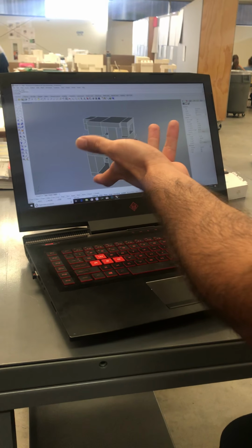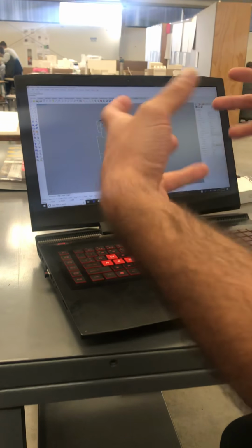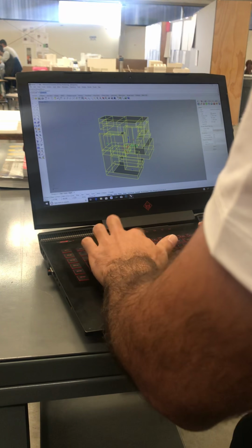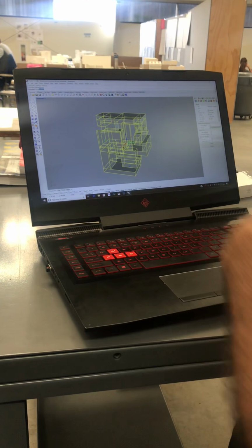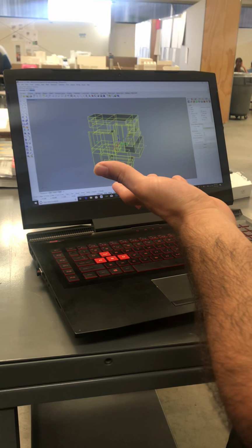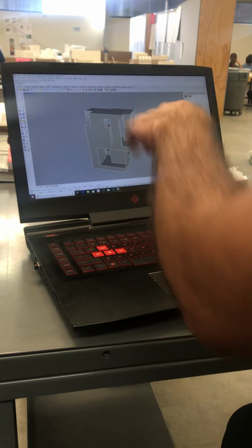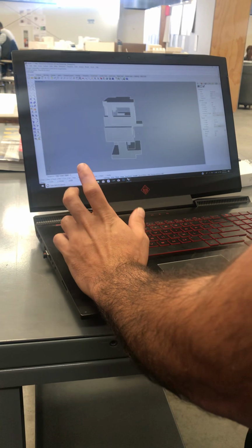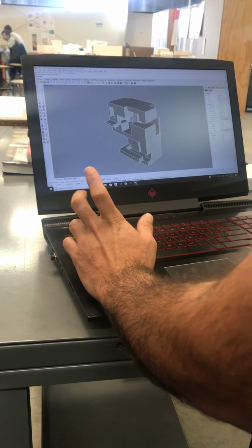of how we made the model. Basically, you made a bunch of boxes and Boolean union them. Yeah. So if I select this and do merge all faces again, you'll see that it just cleans up all the extra lines. So everything that's coplanar is now smooth. So that's one thing that I would do. And then now I can begin my cropping.